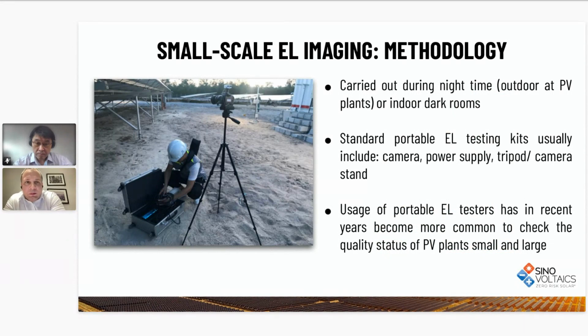After pre-planning of the testing scope of work, so you figured out your plant and the basically workload that needs to be done, you make sure that there are sufficient external power sources to power the test equipment, having also sufficient support on site for the disconnection and connection of modules or strings of modules and the equipment, and then the testing work could essentially start.